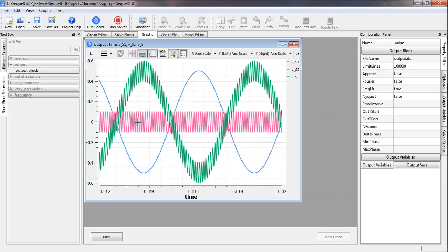This is Vs2, the high frequency input voltage, and this is our Vs, the output of the op amp summer. So notice that this high frequency voltage has got superimposed on the low frequency input voltage, giving us Vs. And note also that Vs has got inverted because our op amp summer is an inverting summer.